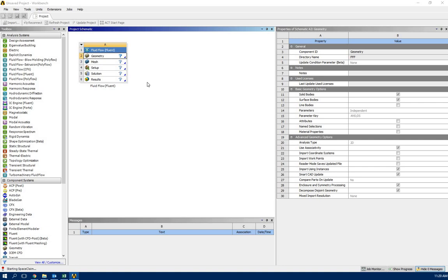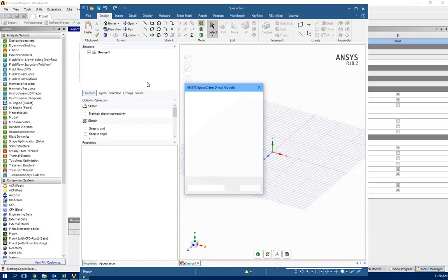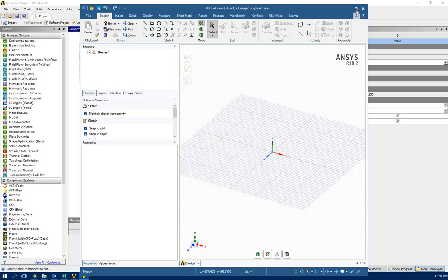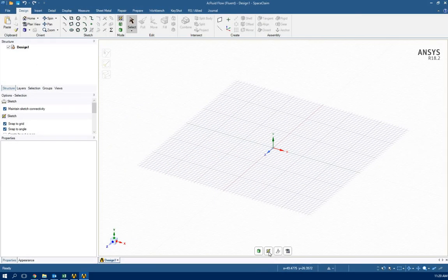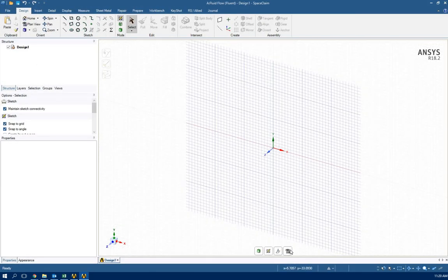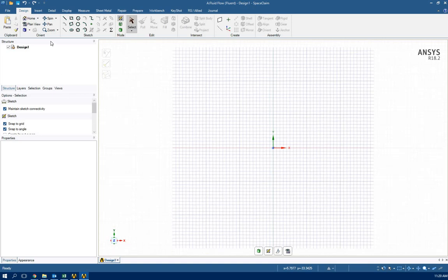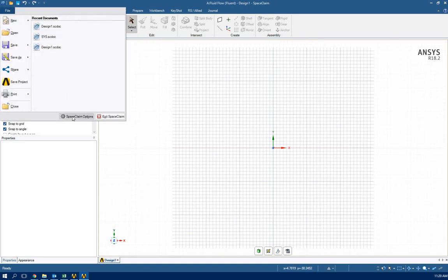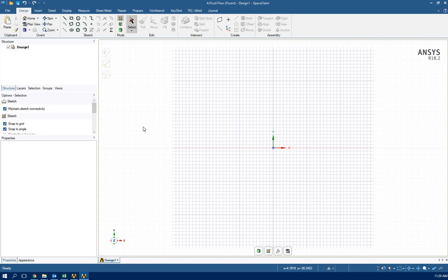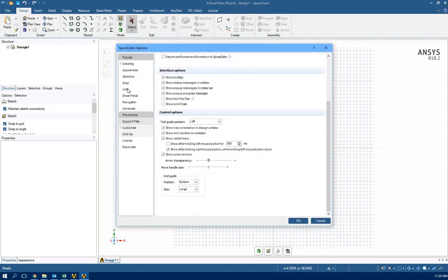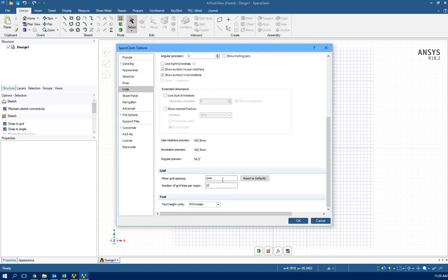and we are going to draw our simple geometry. I'm going to have turbulent flow, so the sizes, everything I'm considering, is going to be adjusted for turbulent flow. So let me change the units to 0.1 meter.